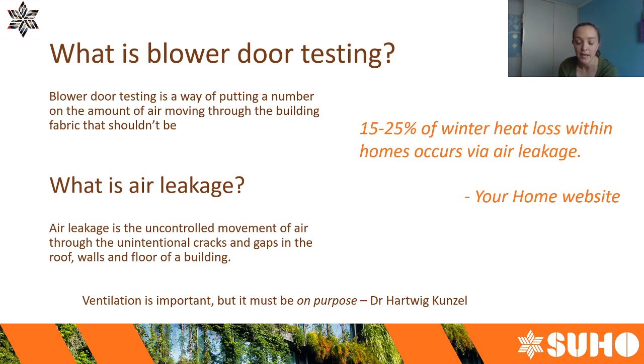We're talking about the air that's moving in and out of the building fabric that should not be moving in and out through the gaps and cracks that are left there basically by the people who build the house. So ventilation is very important, but it has to be on purpose. And the Your Home website states that up to 25% of winter heat loss is actually via the gaps and cracks in your home that shouldn't be there. So blower door testing is a way to quantify that air leakage and fix it.